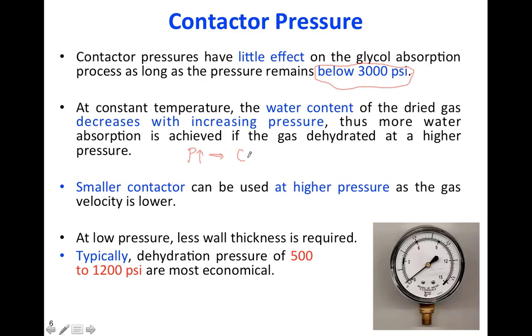So you will have more condensation, or more transfer of water vapor to the liquid phase, which is good for us, and can lead to better absorption. For absorption, we know that always low temperature and high pressure is good. But as I said, we cannot play with the temperature that much, as I already explained in the previous slides. So there is always a certain range for both parameters.